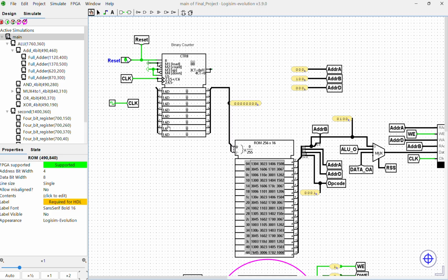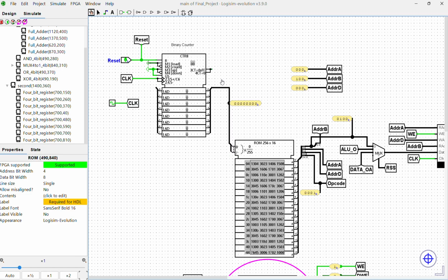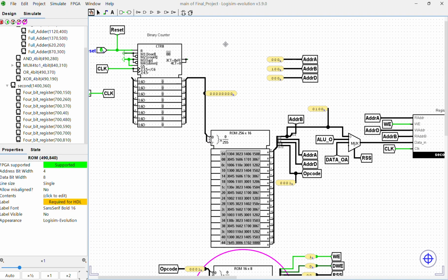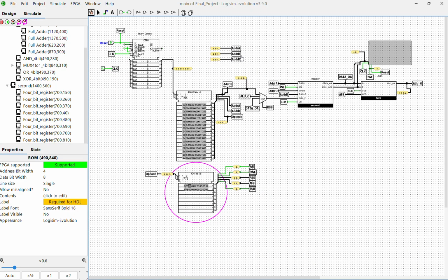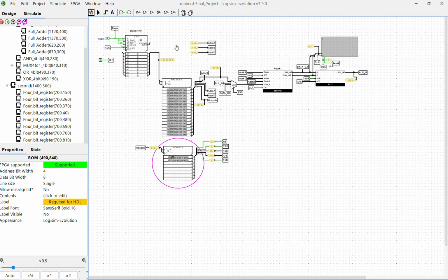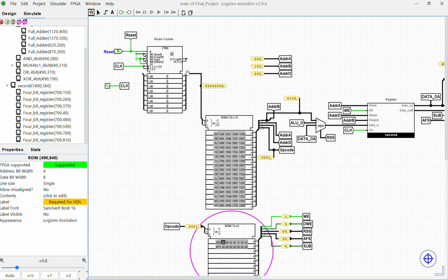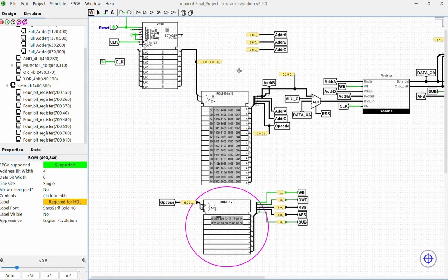This I just grabbed from over here in Logisim. They have a few different components that you're able to use to build the different parts a little bit faster. Like you can grab gates and stuff. The binary counter and the mux are the things I grabbed from there. Going into the binary counter, it runs off the clock, which I have going directly to the binary counter. I use tunnels for most of the other wiring because I think it makes it a little bit easier to read, but this one's just connected directly.